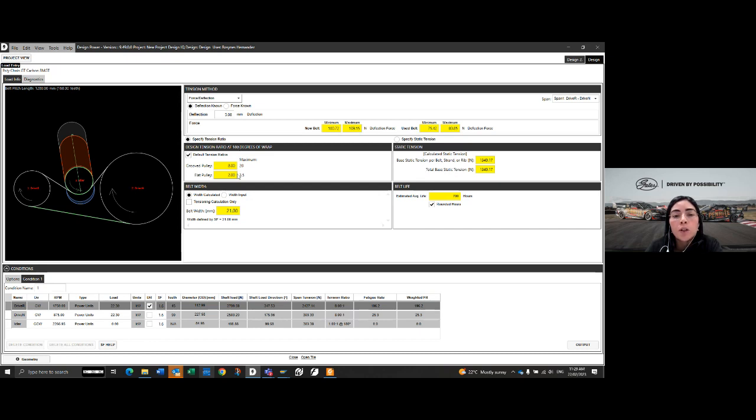So you got the pulleys, the ratio you will need, and then you will also get the width of the belt. So based on what we have provided here, the program tells you that you will need a 21 width belt, which in our case for Pulley Change is a standard one. But sometimes, for example, if the program tells you it's 19, so you will need 19 millimeter, you can just select the next size available for us, which is 21.